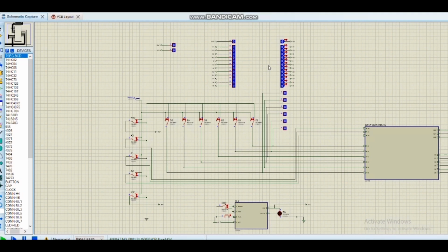So to give inputs, we have to make the r/p pin 1, and we know r/p is run/programming. If run/programming is 1, that means the address selector is taking inputs from our input unit, and when r/p is 0, then the address selector is taking input from the memory address register.